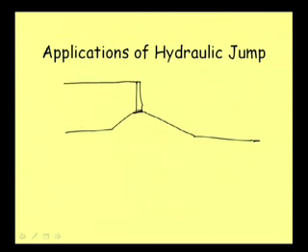is this much, and then this part is called the apron, because as we know that when we will be releasing water or when water will be moving above this part or we are releasing it, water is coming this way, and then this may be a sluice gate like this, and then when we are releasing water it is coming like this, and then it will be moving over this bed.